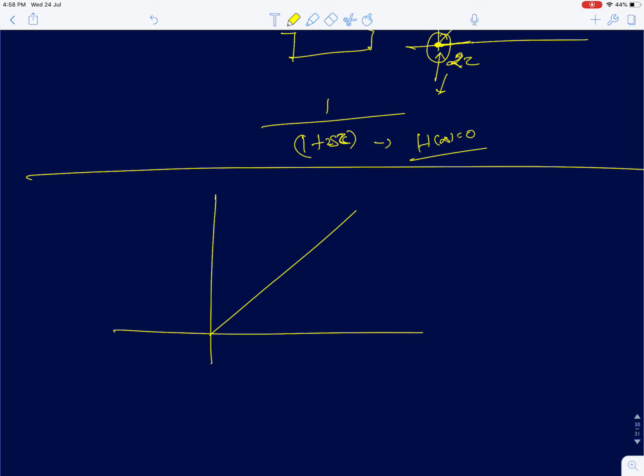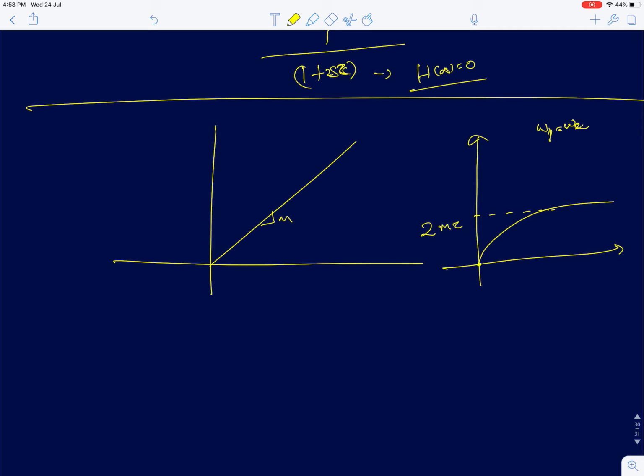So essentially you have t into u of t like this, and the output here is going to reach a value of 2 tau. Here I've assumed m as 1, so let's assume it's m into 2 tau. This will be the steady state value. I'm plotting it for the case when omega p equals omega z and h of 0 is 1, and your input has the slope of m. Now when you subtract these two functions, this will go to a value of 2m tau. So I think it should actually have a response like this. It will actually go to negative values and then go up.